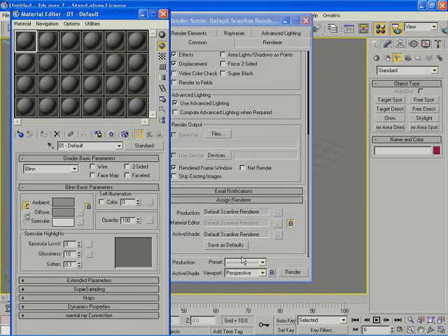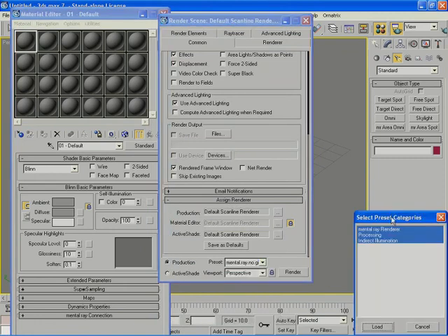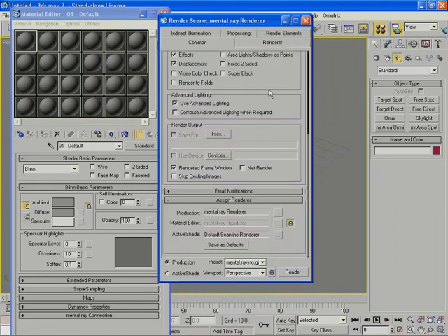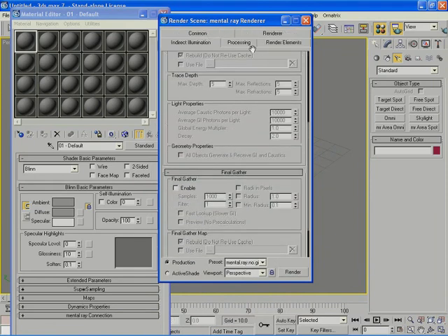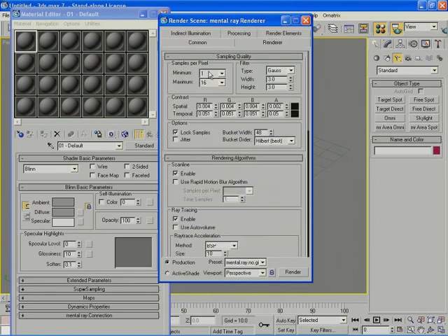The first thing I will do is make sure that under indirect illumination nothing is checked, because this is something that we'll cover later. And under renderer, I'm going to decrease the sampling so that my rendering goes faster. So for now, I'll go to, let's say, 1/4/1, just for now. Now, the first thing I'm going to test ambient occlusion on is a scene that has greeble, because greeble generates a lot of detail in my geometry, and therefore, I can test the occlusion factor there. Once I have a good understanding of how ambient occlusion works, I can apply it to any scene I like.